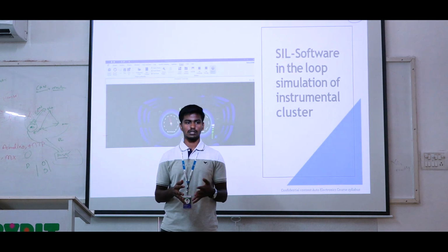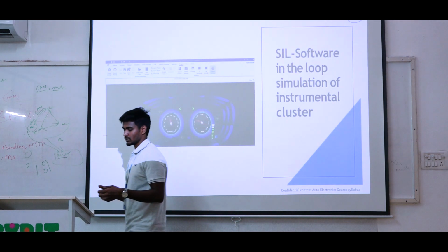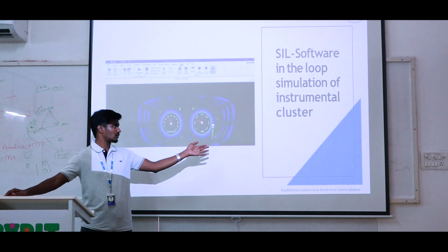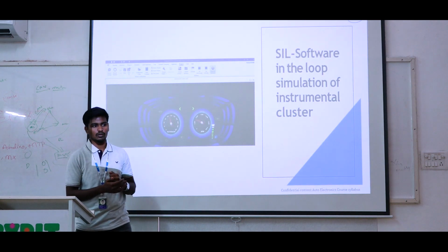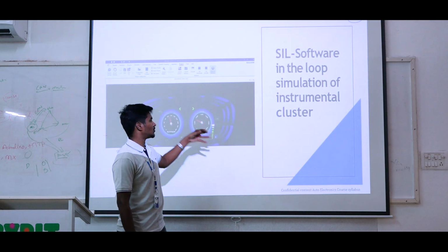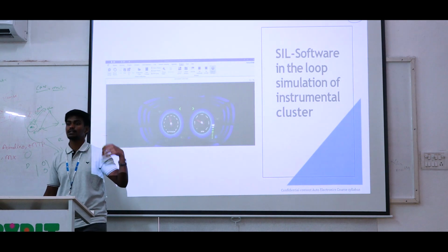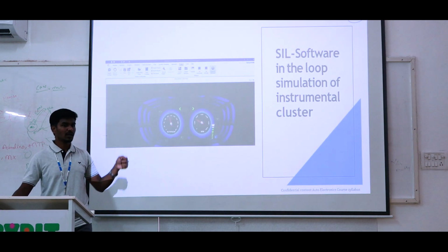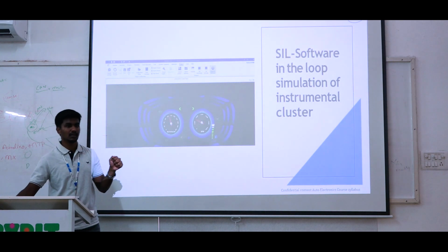Especially with MATLAB simulation, we are able to use model based simulation. Before going to hardware in the loop simulation, they work with software in the loop simulation. Here we are going to create one cluster. We can generate signals and test the signals as per the requirements, as per the verification and validation method.